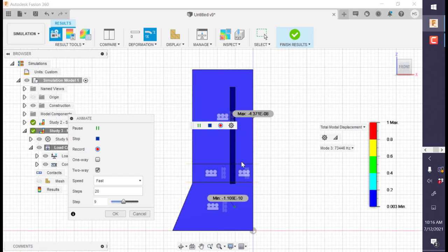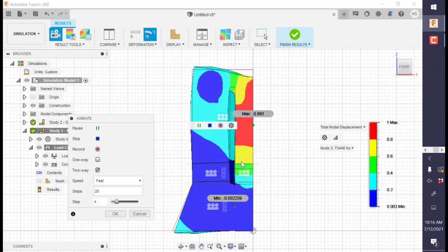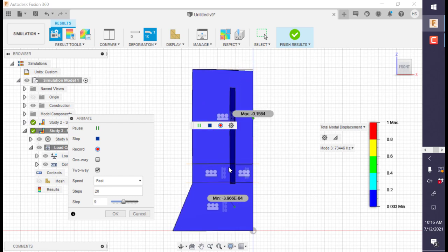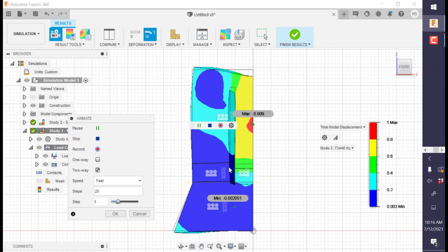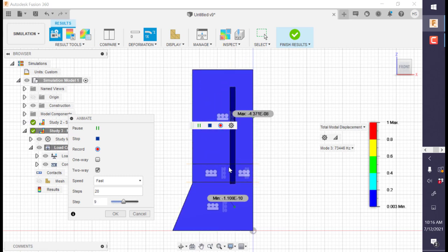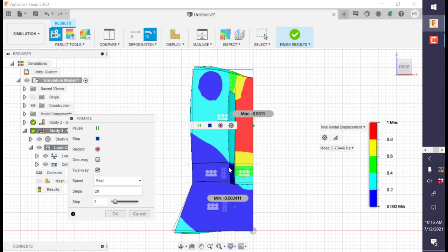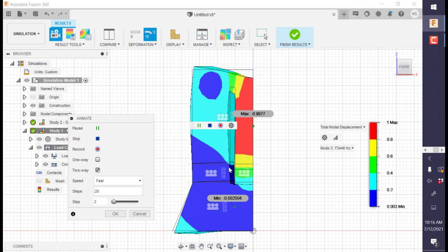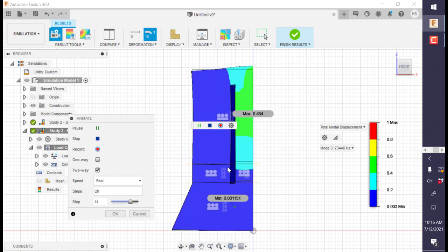When you do your resonant frequency sweep across these frequencies, you won't have a strong excitation, but because of the sensitivity of the piezo, it will excite this mode. Even if it's not the ideal excitation source or placement, the piezo will still excite this mode, and you still will be able to measure its response and the specific frequency.